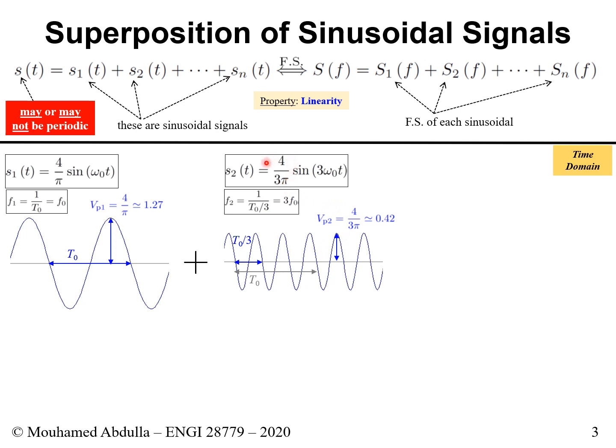And the amplitude here is 4 over 3 pi. 4 over pi is similar to this, except now you divide it by 3, so you're shrinking 3 times. So this is 1.27 volts, and here the amplitude is 0.42 volts. So that's what we get.